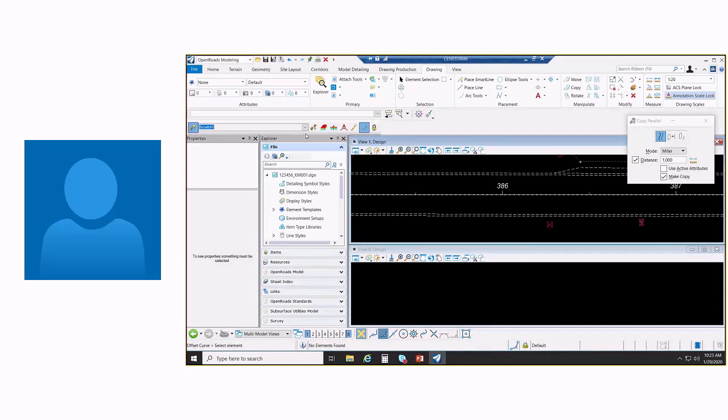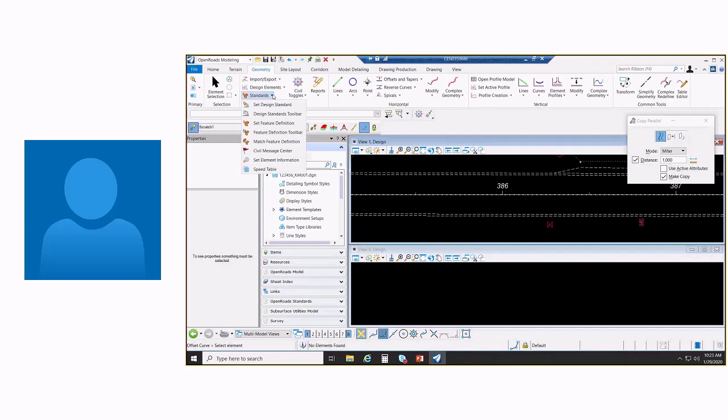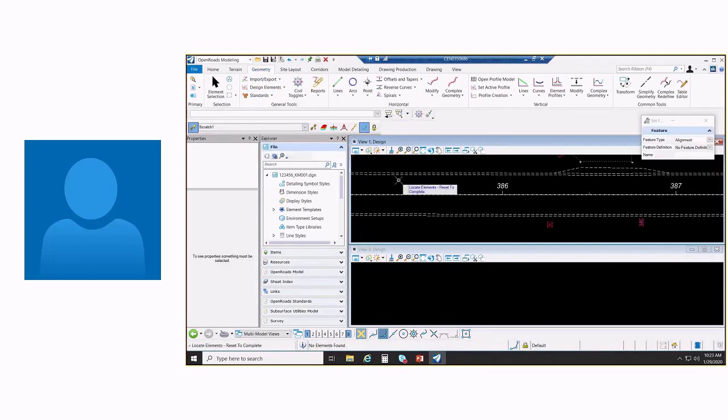Again, we talked about maybe adding some feature definitions that are specifically intended for targeting instead of using the scratch features. So we might add, like an edge pavement, edge shoulder, sidewalk, just some common existing features that you might be targeting. And again, we do have a change request from Bentley to allow targeting survey features, but it currently doesn't allow that. So I'm going to set a feature definition on this and this.